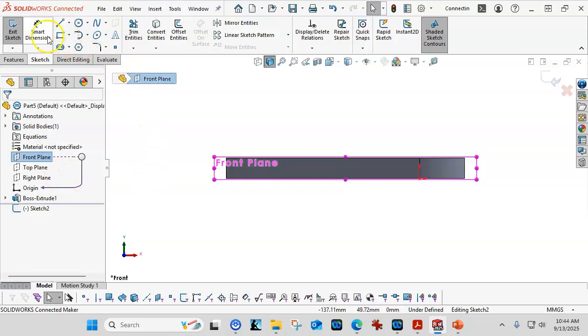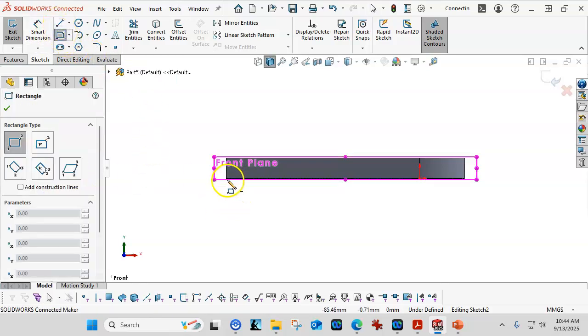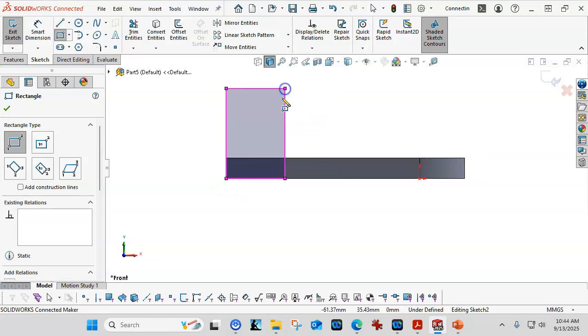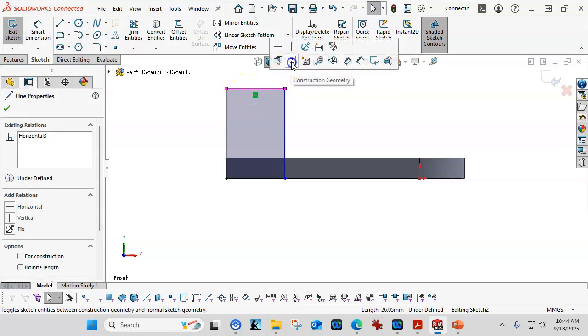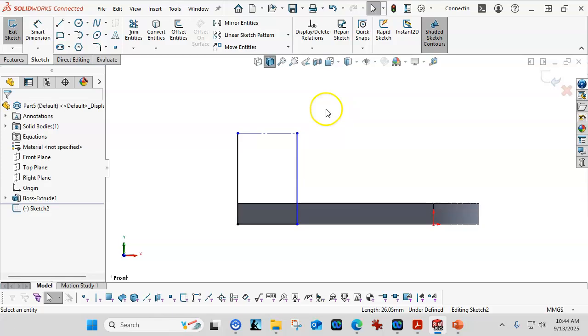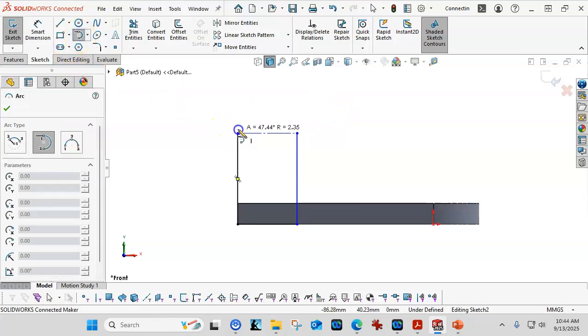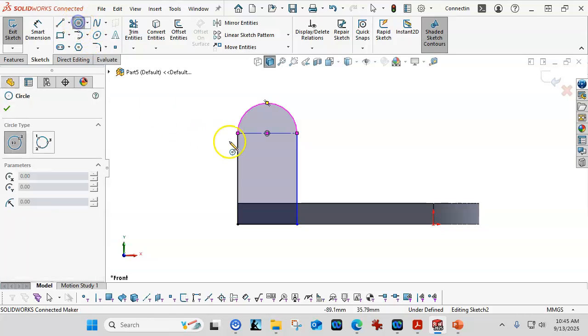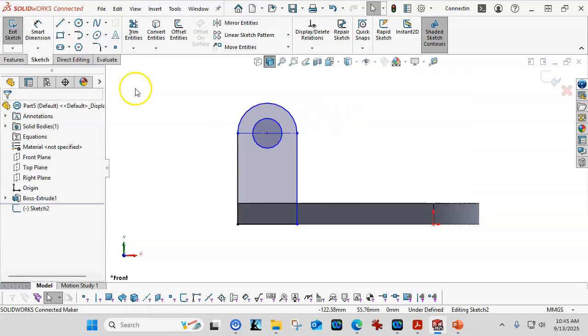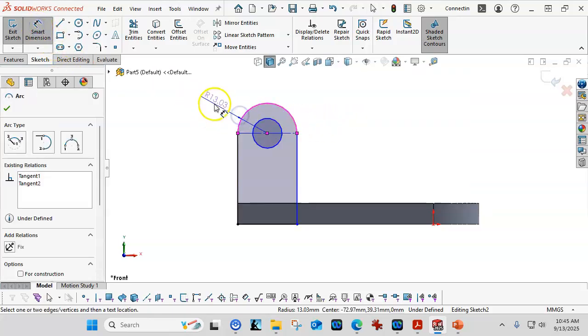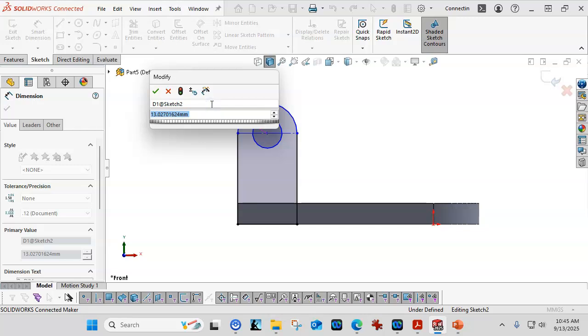All right, so this sketch will do pretty much the same thing. I'm going to go into the rectangle and I'm going to select the line that I'm going to attach the arc to, and I'm just going to stay with tangent arc. And this gave me the diameter. Well, while we're drawing, let's go ahead and finish out the sketch. Make sure I get all the geometry in this time. We're going to go to the smart dimension. It gives me a radius. I know that I can put in the 17 and a half.